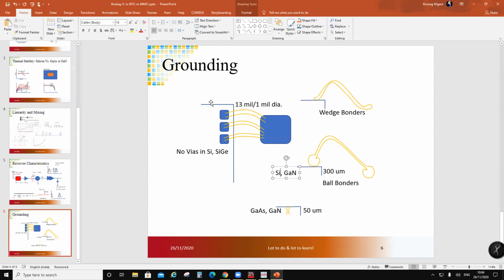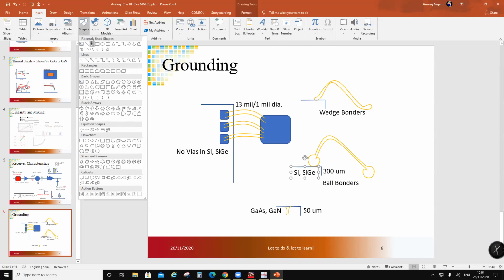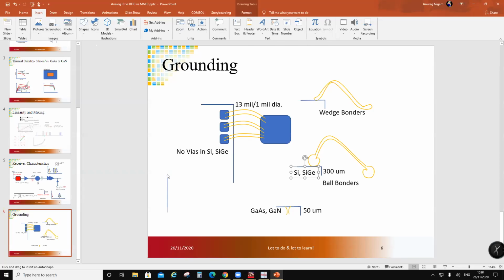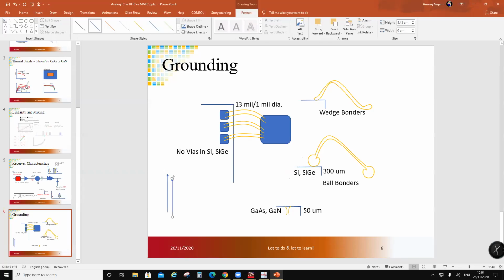You have to bring them through wires. So the gain of the devices is going to suffer because the wires in production are 13 mil long. If you ask for a smaller inductance, they would not let you. So you are left with adding more wires. Is adding more wires advantageous? Yes, the self inductance is going to be in parallel and it will come down. But the issue is the following, and we did this with all kinds of experiments at IBM.